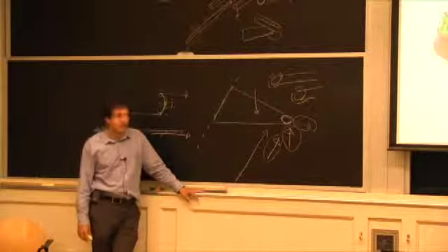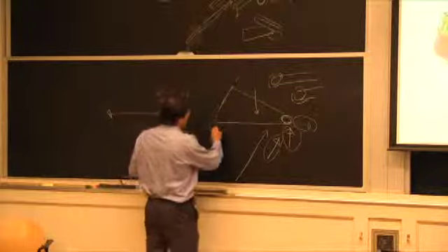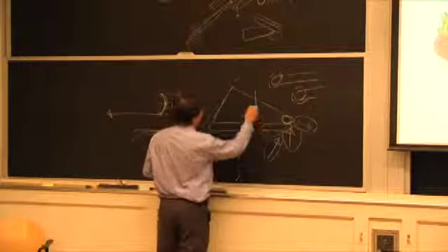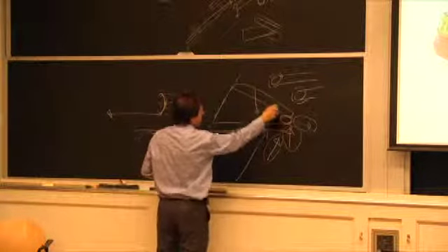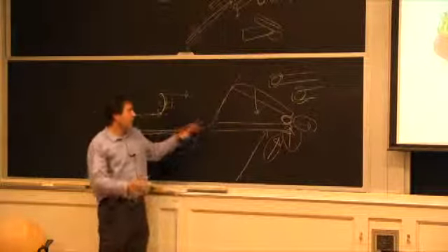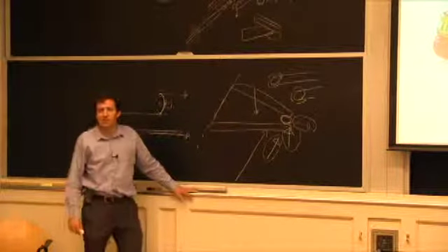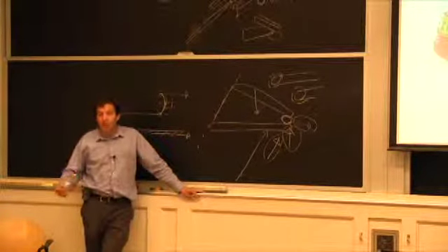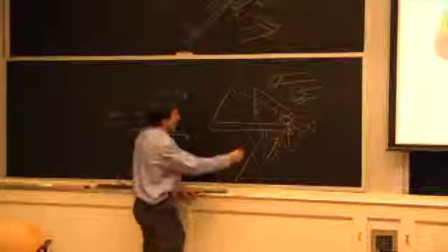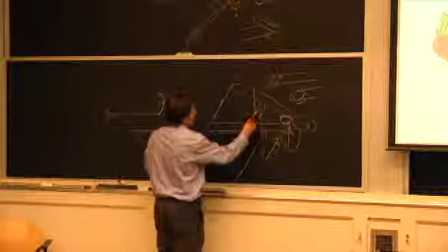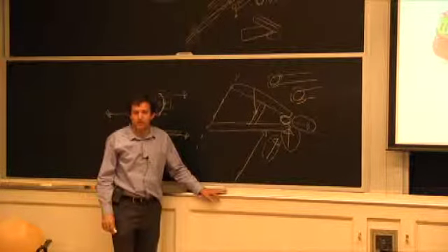So it's still a situation where not everything is optimized, because these tubes are typically the same length all along, even though this one is loaded in compression, and you would want to have it more resistant to buckling, for example, the way I drew it. But it's not practical. You're going to build out of straight tube. So instead, they have some cross members that will help against the buckling capacity and all of this.